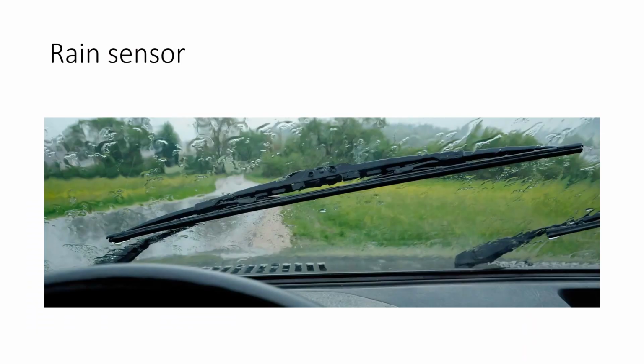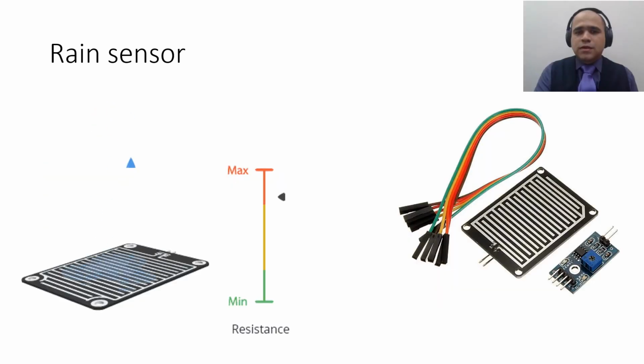How do the wipers of a car start to work as soon as it rains heavily? The main sensor used for these car wipers to move is called a rain sensor. It's nothing but a variable resistor. So when water falls onto this sensor, it changes its resistance because of these interdigitated electrodes. And you need some signal conditioning, as shown here, so that you can convert this resistance into a proper 0 to 5 volt signal.